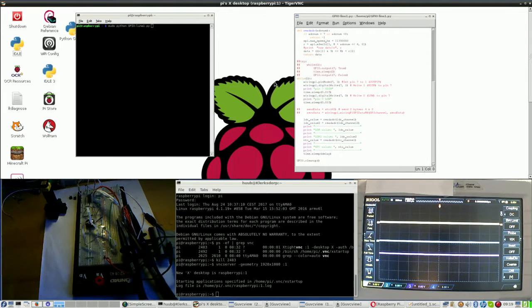Raspberry Pi 1 running Raspbian Linux, and using some electronics in order to read signals, values from a fischertechnik light dependent resistor, photoresistor, and an ordinary one via an analog digital converter to the GPIO of the Raspberry Pi 1, and then a few probes connected to data, clock, data, and slave select.